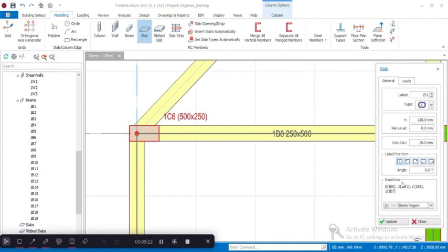Then select slab type as one. We use slab type one for ease of creating the model. We will initially leave the slab type as one for all slabs. Once they have been created and when we are ready to design the slab, there's a function that automatically sets the correct type for each slab, covered later. So each slab thickness, the height, we are using 200 now, and our cover is 30 according to the quick start guide.